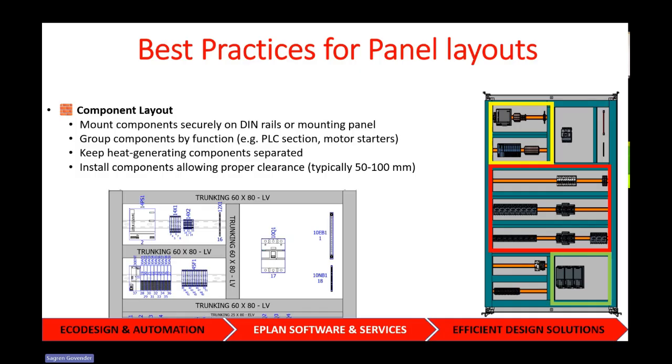Installing your components, just make sure you adhere to the manufacturer's requirements with regards to clearances. Typically a VSD, depending on the size of the VSD, 50, 100, maybe 200 millimeters above and below clearance. So you need to adhere to that. The good thing is that, and I'll show you this later, EPLAN has got tools to manage some of these checks and balances.